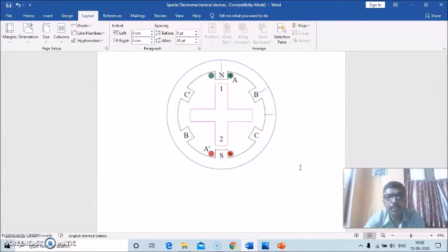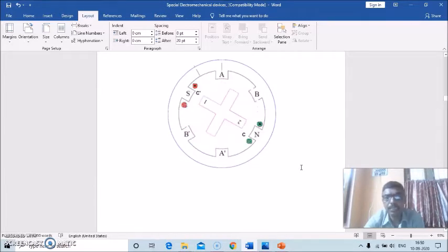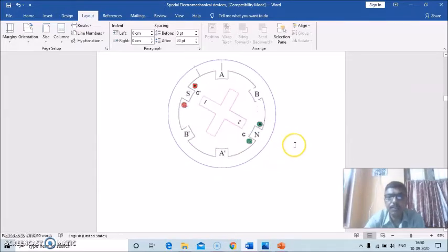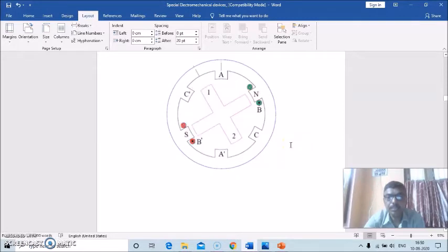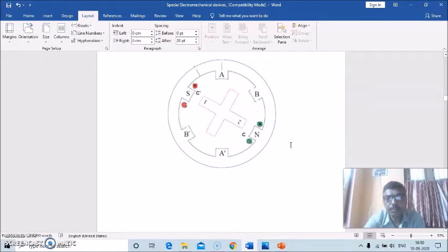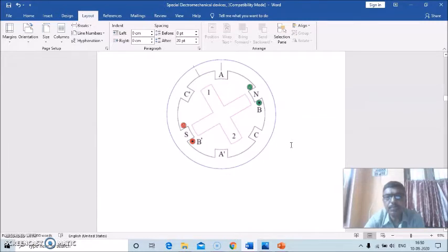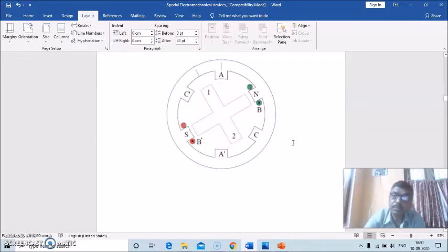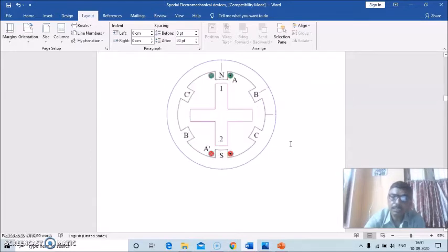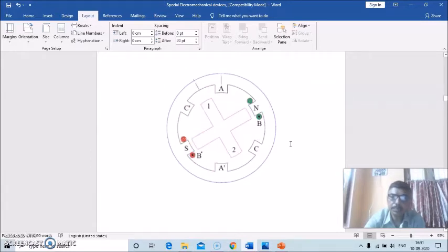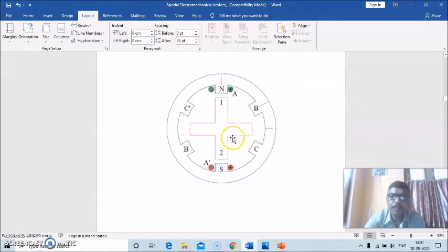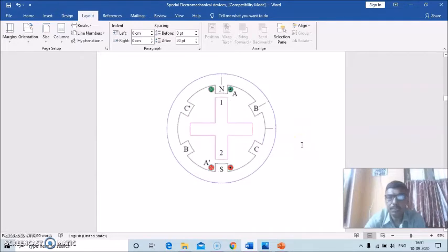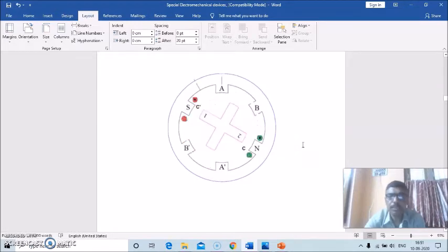See how the rotor position is being aligned with the stator positions, and it is rotating by 30 degrees in each step. Observe it carefully, and you will find this rotor alignment with the stator alignment, and how the switched reluctance is operated. I think this animation will help you understand the operation of these switched reluctance motors.